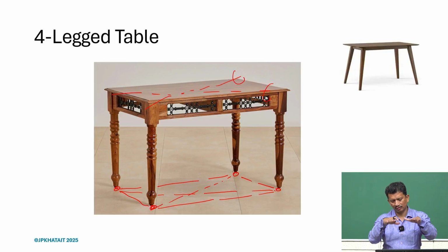The moment the tabletop is compliant, it has diagonal degrees of freedom, so it may be fine, because when we move it to a different location, it deforms and takes the shape of the surface. That is how it works. But because of that, the top surface gets deformed, and anything we attach on top of the table will also get affected. The measurement, everything will get affected because of that deformation. So we should be aware of that.